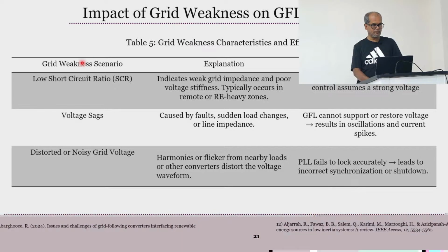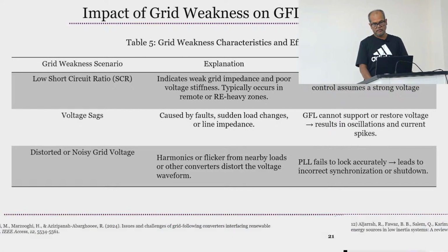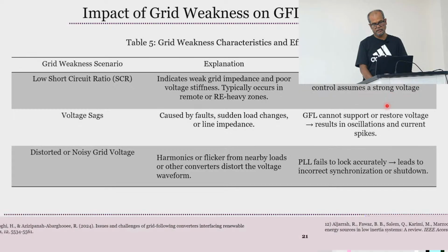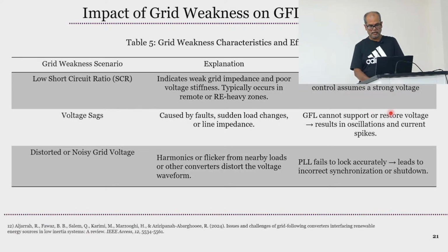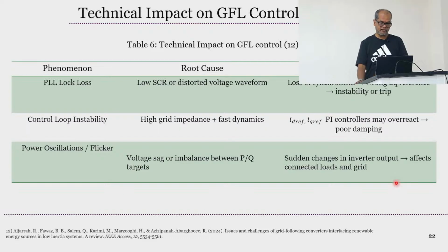And once you have this problem, as I said, the GFL inverter may become unstable, as the control assumes a strong voltage input. If you have a poor one, then it can actually become unstable. It cannot support a disturbed voltage. Again, when you have that weak grid and distortion, the PLL can fail.